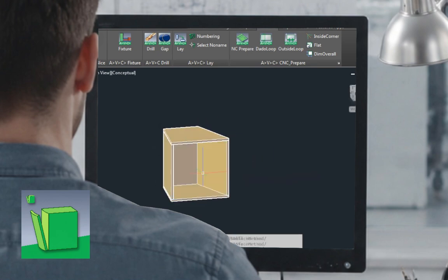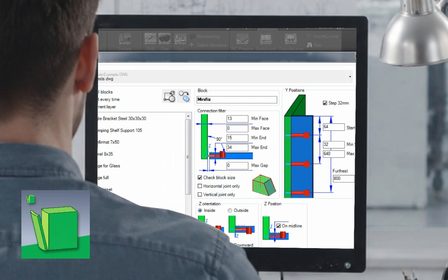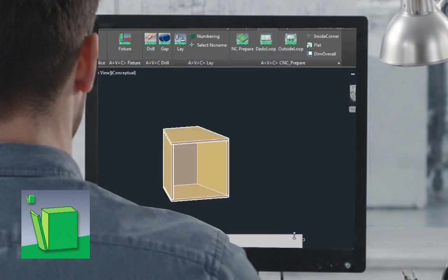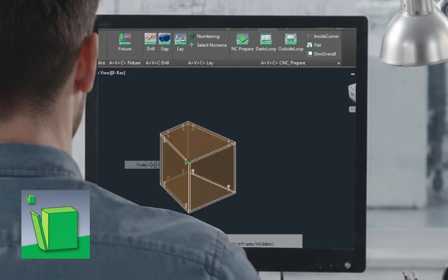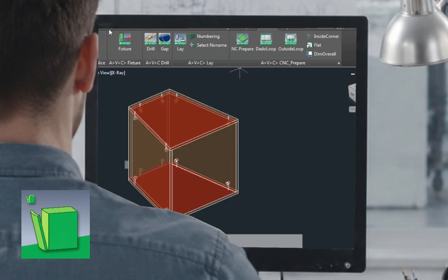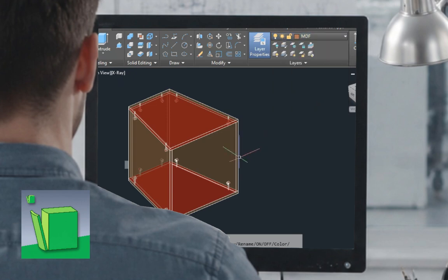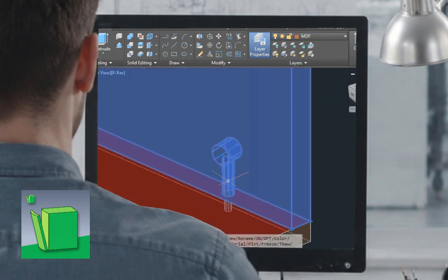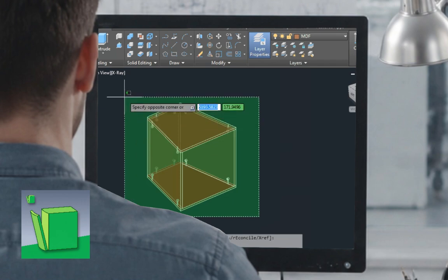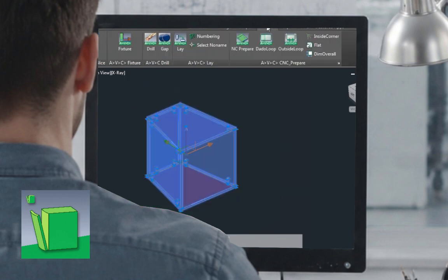We started with a simple box and peeled off surfaces with the required thickness. In standard AutoCAD, getting the same result would take many more steps. You would need to create faces manually or use the standard slice command, calculating distances and building construction geometry first. And if the object has a complex or curved shape, the amount of manual work increases even more, along with the chance of making mistakes.